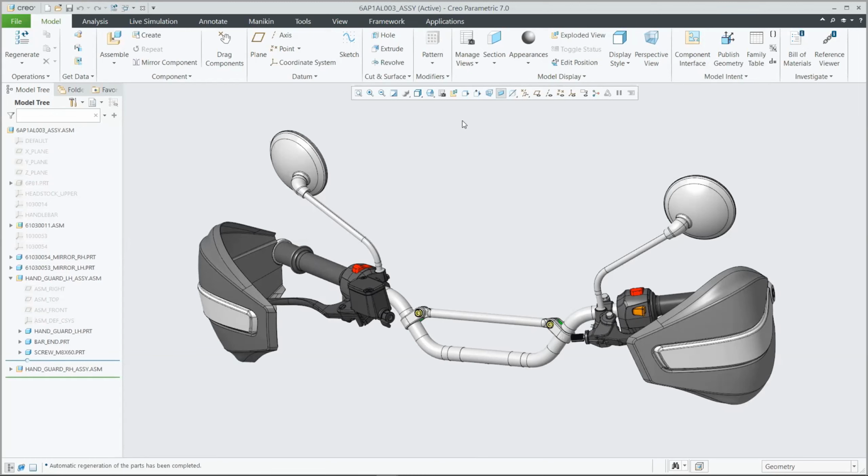Use that along with the flexibility to create and add points to build out any of those curves initially. You can use the analysis to look at the transitions. And then once you have your curves set up, start utilizing those to create your surfaces, generate your quilts, merge it all together and solidify it, and then do any little cleanup work to add rounds and chamfers or things of that nature, and utilize that in whatever products and designs it is that you're generating.